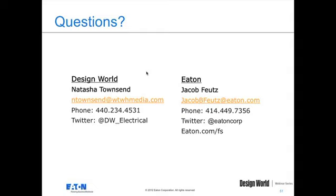Okay, thank you. And I have one more question. As control system architecture shifts and communication capabilities expand, how do these changes impact functional safety considerations? For example, how does an integrated HMI PLC impact functional safety applications? Yeah, I think one of the important things to recognize is, right now for a lot of machine builders and their control systems, safety is a bolt-on. So they have their standard control, their PLC, or their HMI, their operator interface, whatever is performing the logic, the SCADA, all the advanced functionality. And then the functional safety is bolted on to that. So you have a safety relay or a small safety controller that is bolted onto the side of that application. And as things evolve here, people are going to have to consider moving more towards products that can be used in both their standard and their safety applications to perform that more seamlessly.